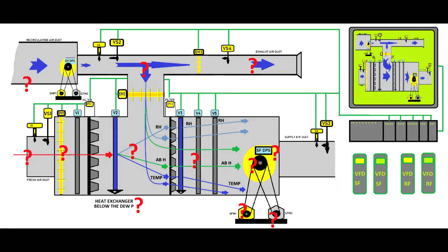If the air handling unit designer doesn't have service experience, then you will design an air handling unit which will be very hard to service and maintain. And if you look at this air handling unit, everything that changes its color in red are the probes, the actuators, which are actually controlling the airflow and the temperature or the air humidity.